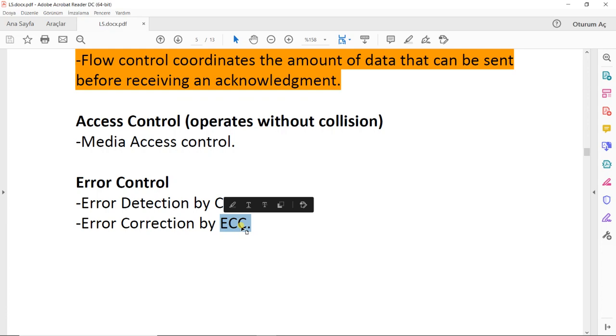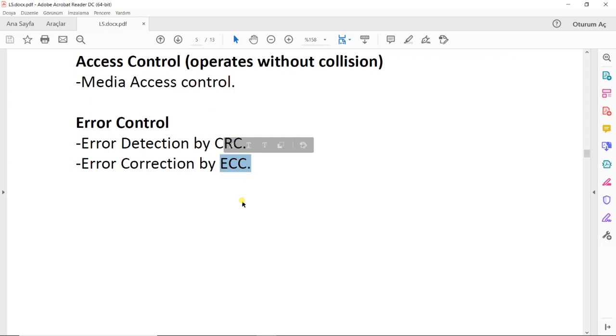Examples of these codes: we have convolutional codes, turbo codes, LDPC codes, Polar codes, and many others. But the most common ones, for example, in Wi-Fi, what types of codes do we use? In Wi-Fi, we use LDPC codes. In 4G networks, what types of codes do we use? We use turbo codes. These are the codes that help us correct the errors. In 5G, what types of codes do we use? We use two types, one for control, one for data. For control, we use Polar codes. For data, we use LDPC codes.